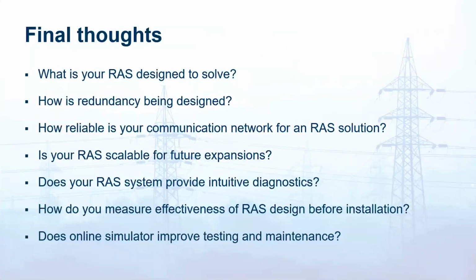With this slide, I would like to summarize all the key design questions that help in designing a RAS system. What is your RAS designed to solve? Is it a thermal overload issue or a voltage collapse issue? How is redundancy being designed? Is it a RAS that is limited impact or other RAS? Is single point of failure allowed?